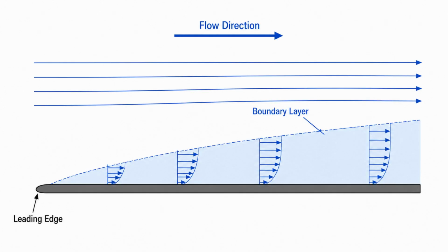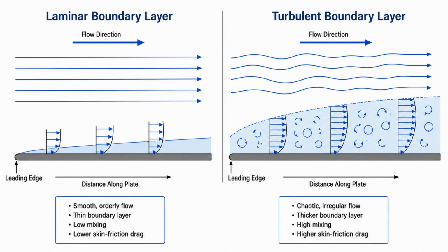The boundary layer doesn't maintain the same thickness across the wing. At the leading edge, the boundary layer is extremely thin. As the airflow continues downstream, viscosity continues slowing nearby layers of air. Because this slowing effect spreads farther away from the surface, the boundary layer gradually becomes thicker. This means that the farther downstream you move, the thicker the boundary layer becomes. Not all boundary layers behave the same way, and there are two types of boundary layer with distinct characteristics and features: laminar boundary layers and turbulent boundary layers.